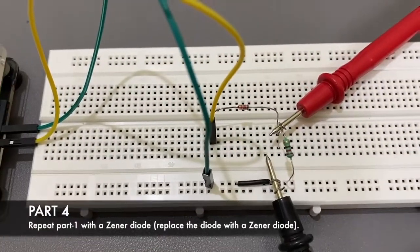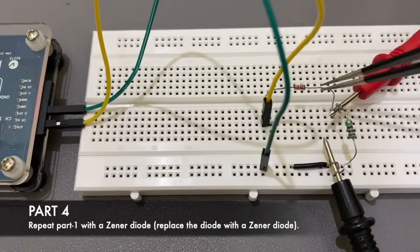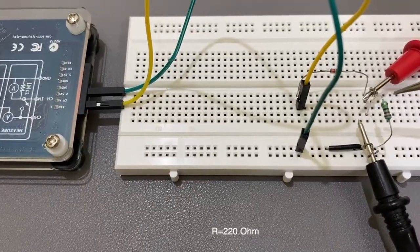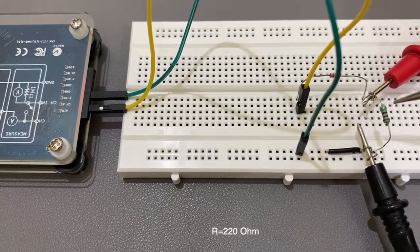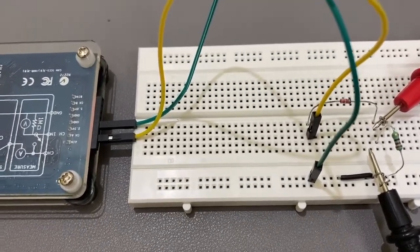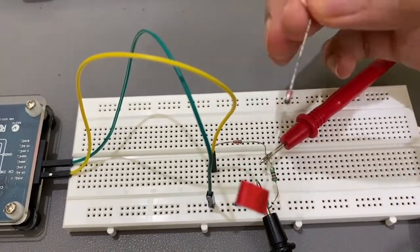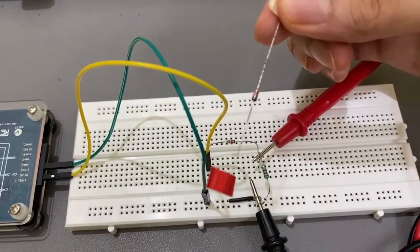This circuit is very similar to the circuit which I used in the previous part. The only difference is that I am using a Zener diode instead of the real diode, which is a p-n junction diode, and I'm using a resistor of 220 ohm. In the PDF it is mentioned as a 200 ohm resistor, but I don't have that, so I'm using 220 ohm. A Zener diode is similar to the real diode. The only difference is that a Zener diode has a breakdown voltage in the reverse bias condition, which is similar to the barrier voltage in the forward bias condition.